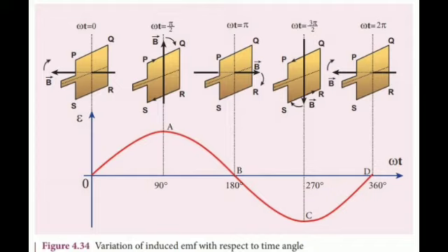Since they are connected in series, EMF are added up and the direction of total induced EMF is given by Fleming's right hand rule. The direction of the induced EMF is at right angles to the plane of the paper. For PQ it is downwards and for RS upwards. Therefore, the current flows along PQRS. The point A in the graph represents this maximum EMF.